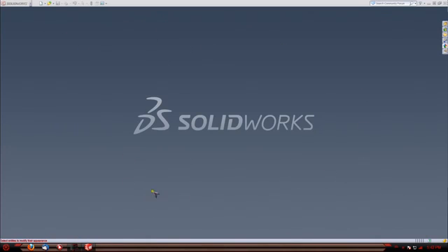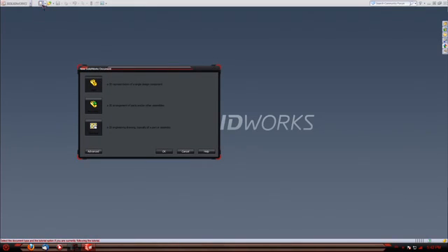When you open up SolidWorks, you've got a blank screen. First thing you want to do is hit the New Page button. And you have three options to pick from: Part, Assembly, and Drawing. Drawing is essentially what you do in AutoCAD, if you're familiar with that. I don't recommend drawing in SolidWorks because it kind of defeats the entire purpose of the software to begin with.